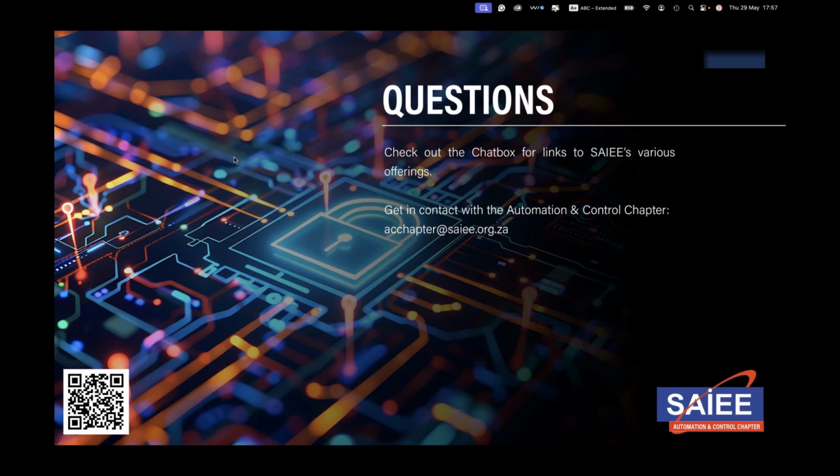Yes, for me, if a protocol is obsolete, to be honest, I'm not a fan of using obsolete protocols. Even when you hear the very OEM of those protocols has advocated for customers to move away. So I'm not a fan of it. DNP3, we've seen that there is a version of it that is IP based, and it's mostly used closer to the municipalities or smaller substations.